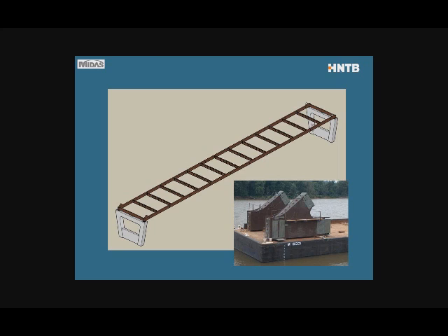So the knuckle joint sits on the bearings, but when you have bearing replacements, you actually have to put in some jacks to lift and take the load off the permanent bearings, and so that's another tricky load case that exercises the end floor beams quite a bit. You can see in the inset, those are the actual knuckle joints. Again, to give you a scale, the inside of the tie girder is 7 feet tall. So what looks tiny in the renderings is actually a huge structure.